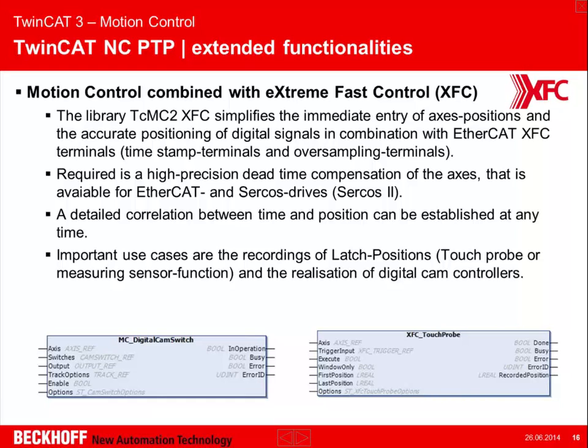And which is behind, we have of course EtherCAT as a field bus, and we have timestamp inputs and outputs, and also oversampling terminals which are supported in this special application. And one of the applications inside we do is dead time compensation. So with the directly using of the timestamps in the drives, and also of course in the master, we can do a time measurement, and with dead time compensation we can also support dead time compensation in the different axes.